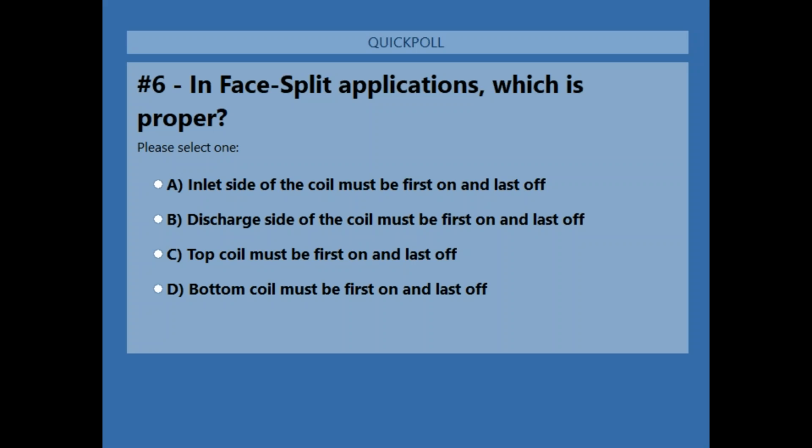There's a piece of pipe between each of those 4 major components, although I don't know what we call the pipe between the metering device and the evaporator. It's so short, no one ever gives it a name, I don't think. But the distributor tubes are what they are. After your metering device, you go into the distributor and into the distributor tubes, and that's not something you modify or change in the field. Right.